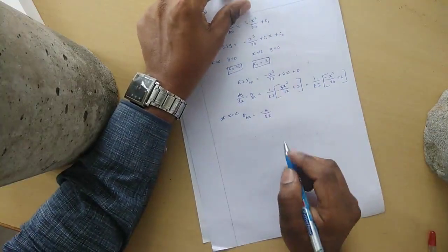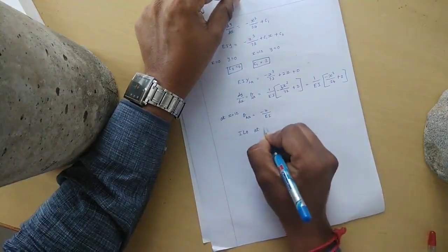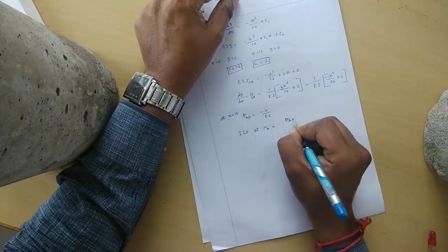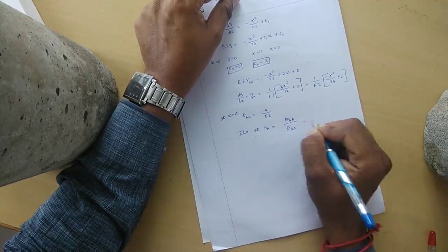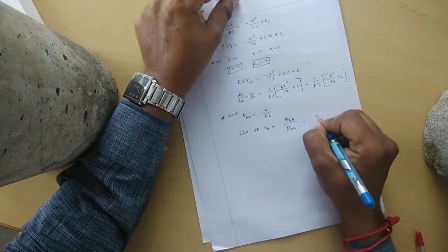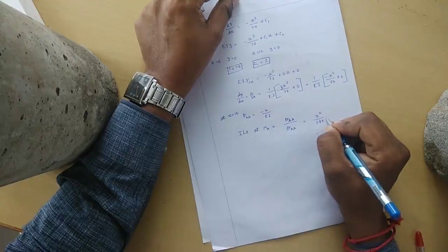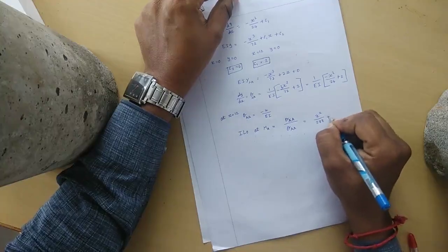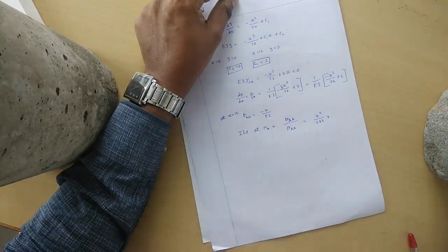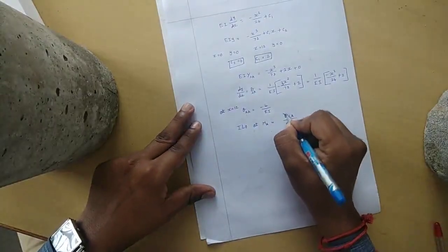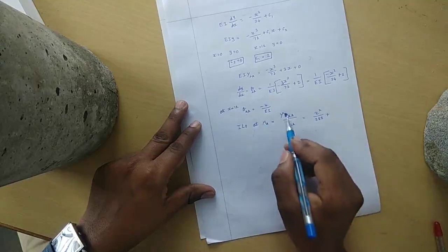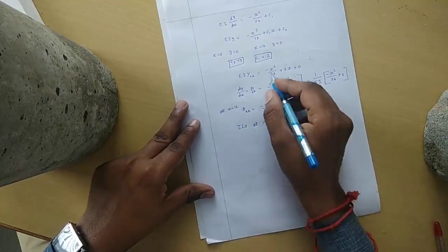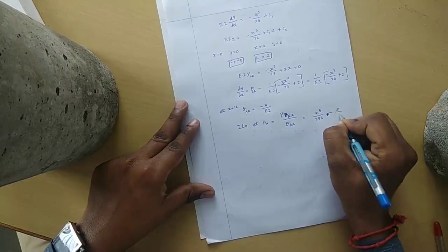As usual, we know that if we want to calculate the influence line ordinate at MA, we need to consider the value theta xa divided by theta AA. If you substitute in this equation, then the value will become x square divided by 288 plus, since we need to calculate the yxa, that is deflection, so we are taking yxa. We substitute in this equation and get x cube divided by 288. Since it is minus into minus, we get plus. Here minus x divided by 2. So this is the equation.